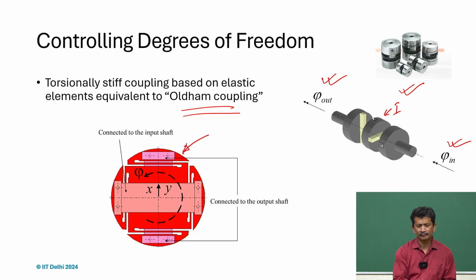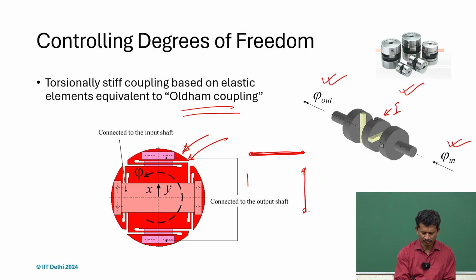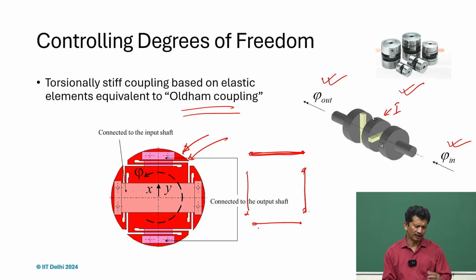If we understand the constraint, the flexible constraint, and apply a linear constraint, what we can see here is that there are 4 of them, just flexible parts. So, 1 on this side, 2, 3 and 4, and it is a symmetric design. Again, one can say it is an over-constraint, but it is symmetric and flexible. So, it will readjust, and the angle, the rotation we want to transfer to the other side, or even the load, it will not provide any kind of moment transfer or displacement transfer from one side to the other, except the rotation which is desired. So, phi. So, this is the constraint we want, and each one of them will provide that.